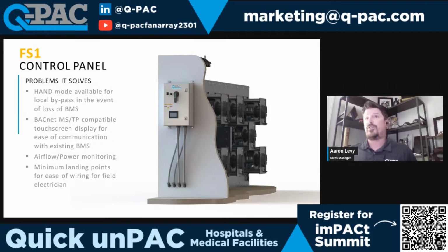So in the event that you lose BMS or something happens to the PLC, you can switch that to hand mode. As long as the fans have line voltage going to them, the fans generate their own +10 that we can modulate with the local potentiometer. So that gives a lot of peace of mind that if for whatever reason BMS goes down, you can run that in hand mode and go.